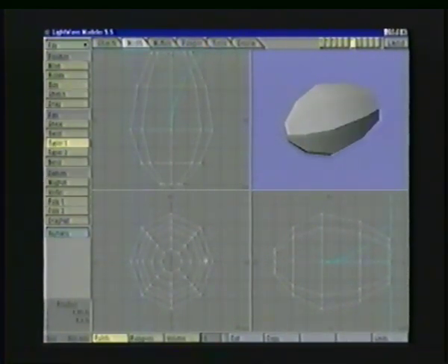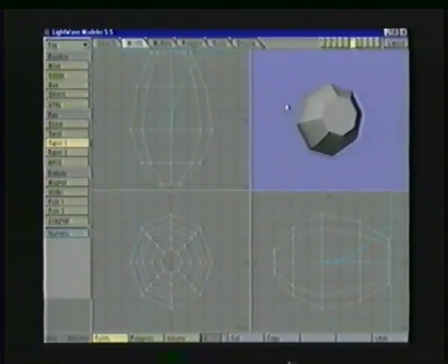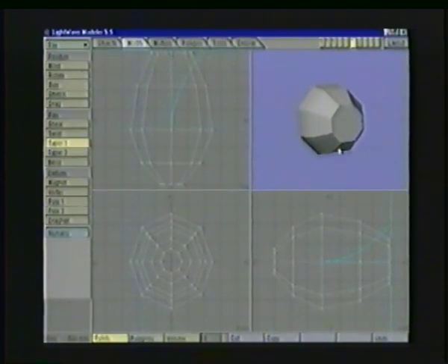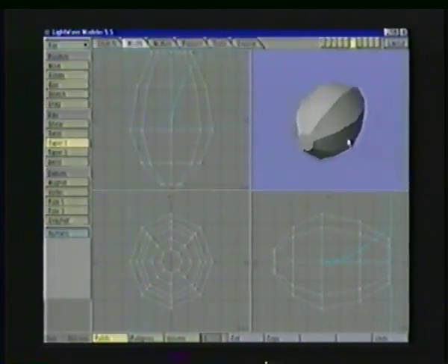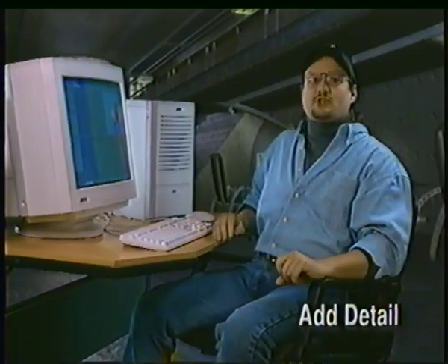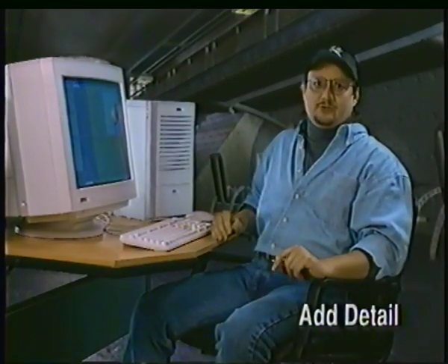And it should be about right there. You can see how nice and easy that was to taper evenly in two axes at once, the y and the x. I didn't have to worry about it. Taper 2 is there because sometimes you don't want to taper evenly, and we'll be using that later on. Now that we have our basic shape, let's add some detail to it.